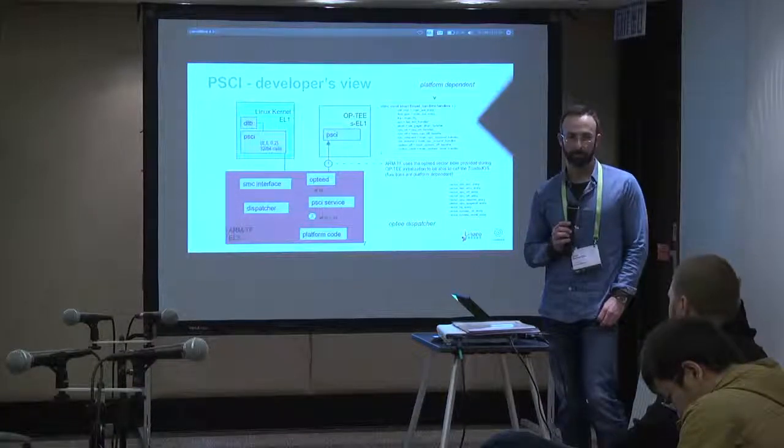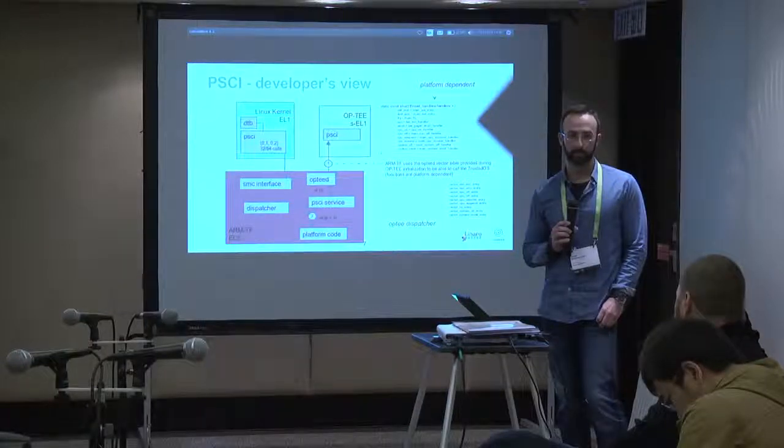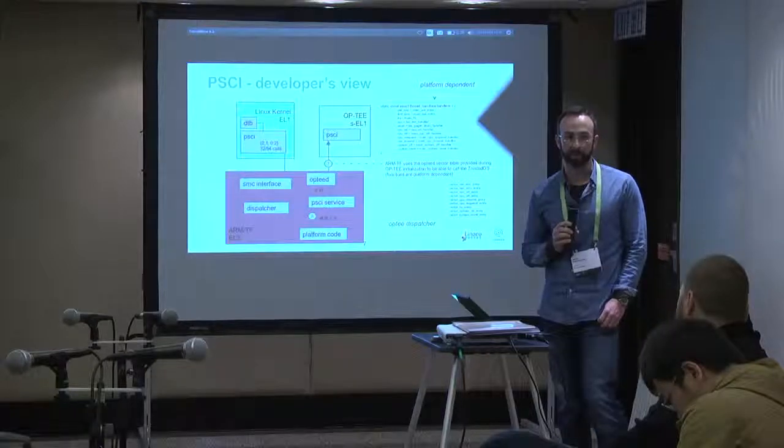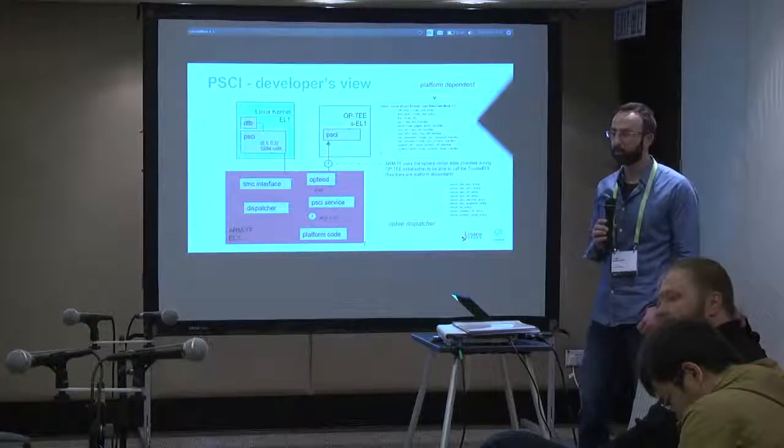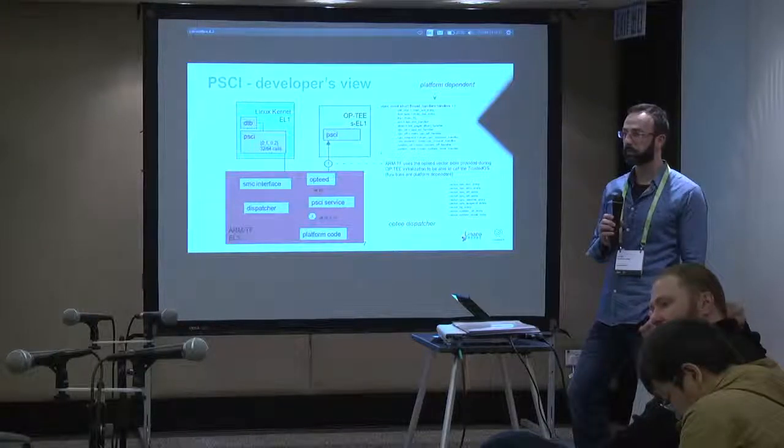So if you're not using OP-TEE or something, and you just have trusted firmware, the trusted firmware itself is SMP aware. Yes. Okay. I mean, that's my understanding. Yes. Trusted firmware runs on every core. On every core. Yeah, the SMC will go to trusted firmware on the core you're running on.